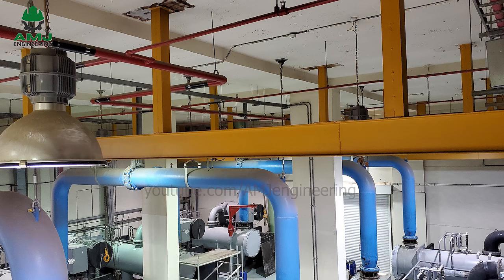Upright sprinkler heads are efficient at dispersing water between obstructions. Thus, they are frequently used for rooms that are inaccessible, such as mechanical rooms and in warehouses and industrial spaces. They are also often applied in structures with open ceilings.